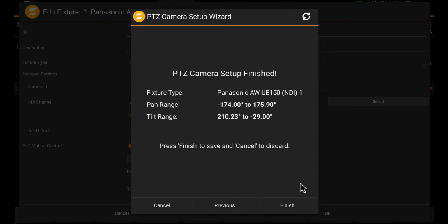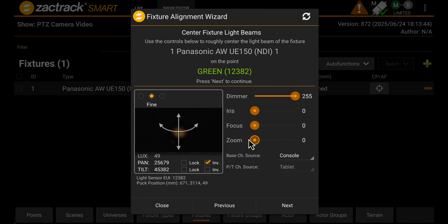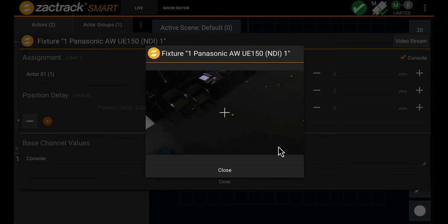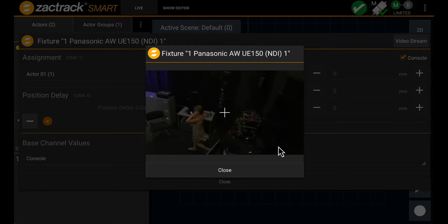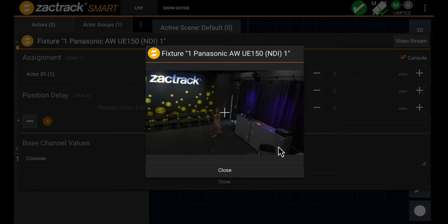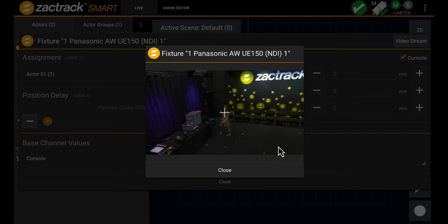But some cameras struggle with that kind of constant precision, especially during live tracking. The result, a jerky motion caused by the camera's internal buffering. Relative control fixes that. Instead of absolute positions, the camera receives directional movement, a little left, a little up, now stop. It's more fluid, more forgiving, and much easier on cameras that can't keep up with the high-frequency tracking data. Whether your stream comes from a direct network connection or a converted HDMI signal, we've got you covered.